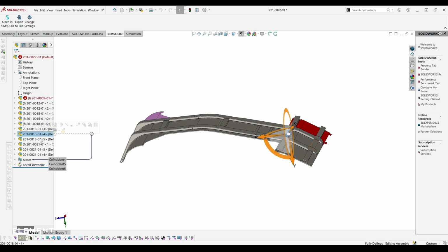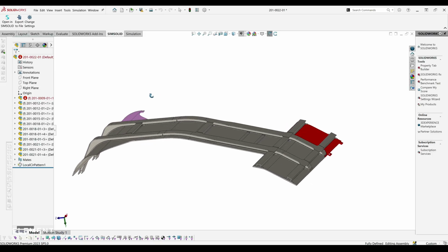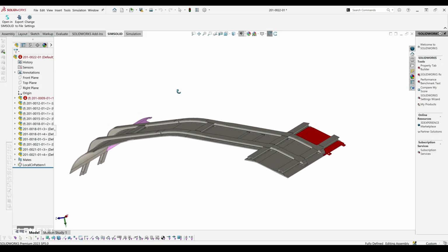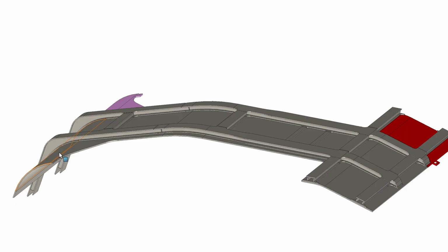So these are all sub-assemblies that would, again, have their own drawing pack. And then the other part of this as well is the jigs and fixtures. A lot of people don't understand or appreciate that when you go to production, you'll need to make a fixture that may hold all of this in a particular spot. When you start to weld it, it basically stays in that spot.